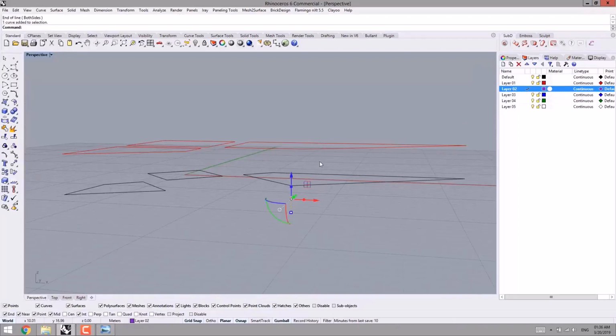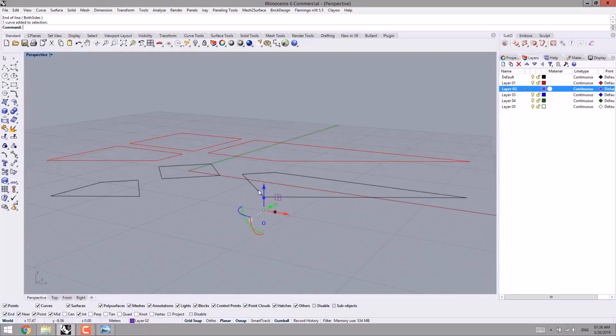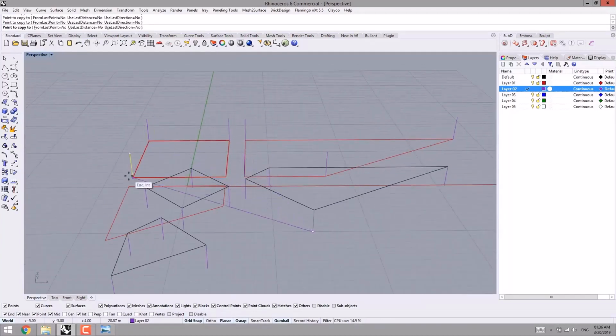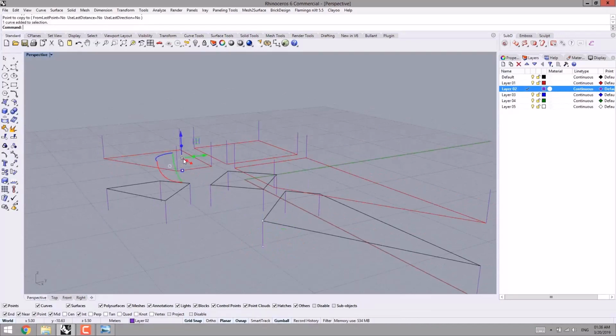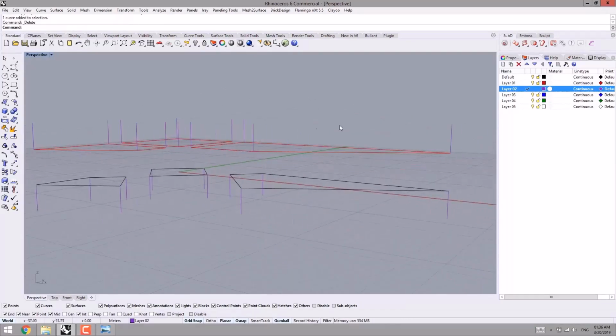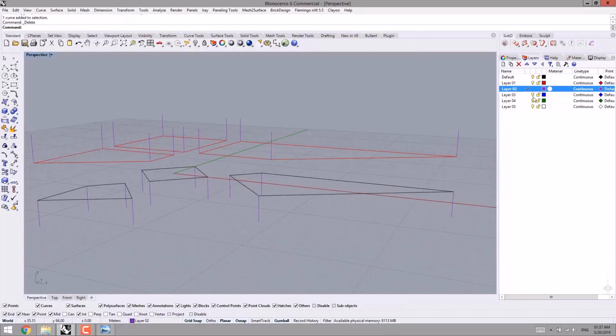So then if I blend these two lines with each other, we will have the blended curve, not the extra lines. I select the line, I make a copy, then I position it at the intersections like this by using copy. Again, I start the command of copy for the other parts of the intersections. I fill the other parts by the vertical line. One of them is not needed. I remove it. Well done.